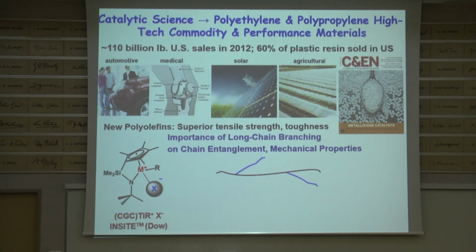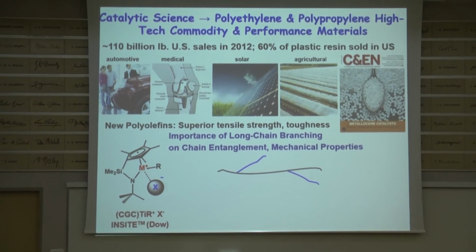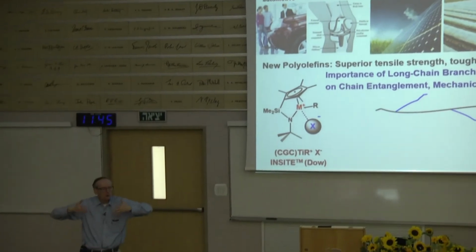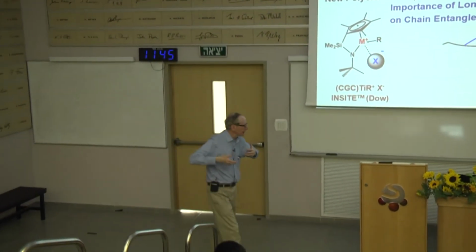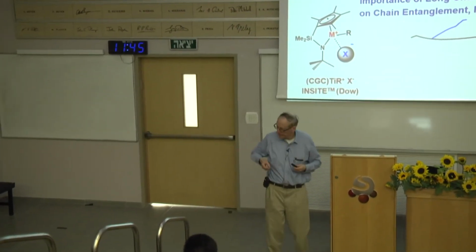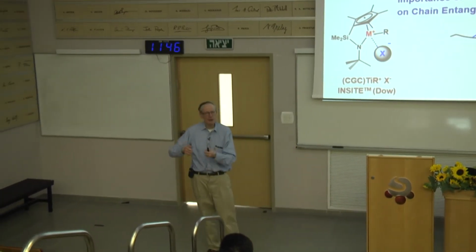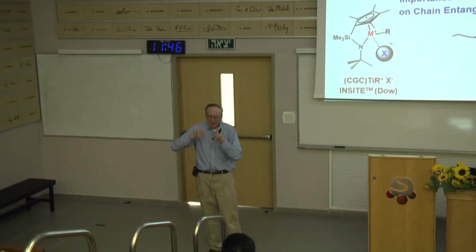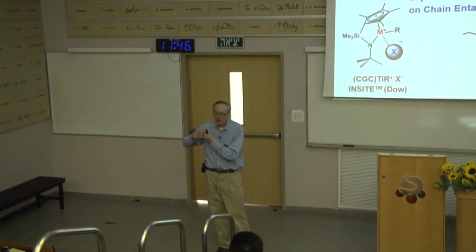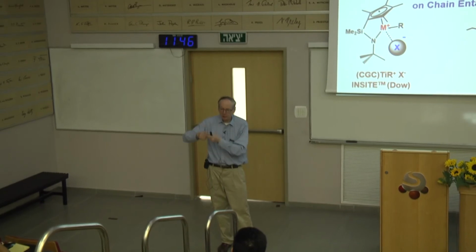And the strength has to do with a lot of physics, a lot of how the chains entangle. So imagine if I have chains that have branches and the branches entangle, so the physics of pulling that entanglement apart translates into remarkable strength for remarkable light weights. So normally at this time in the lecture, I look for a trash can, because garbage bags, and I know that sounds trivial, but that's an example of some really interesting polymer physics to make something that strong.